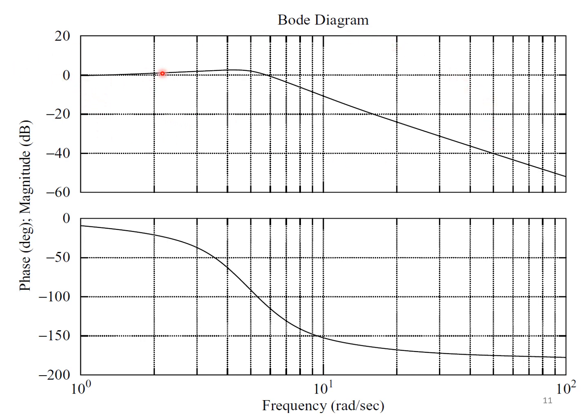The first one represents the magnitude plot, wherein the reference is taken from 0 dB, and similarly the angle here is represented by taking the reference to be minus 180 degrees. So these two are the plots which are drawn using the semilog graph sheet. This is the semilog graph sheet which we'll be using to draw the Bode plot for the stability analysis in the frequency domain.